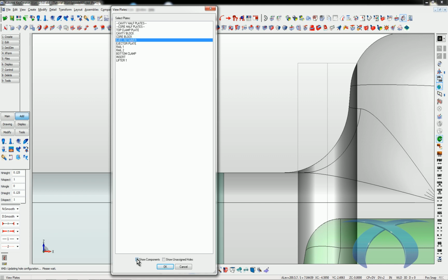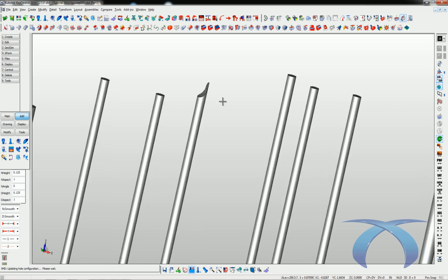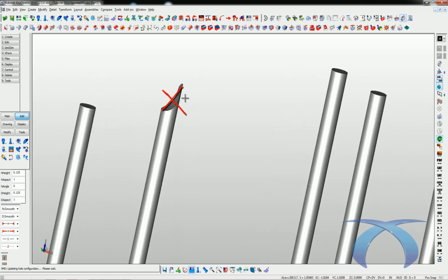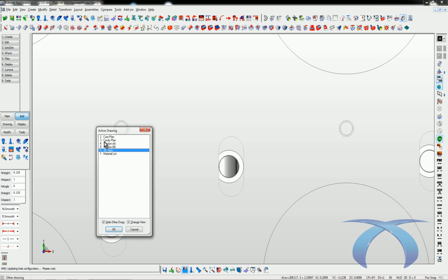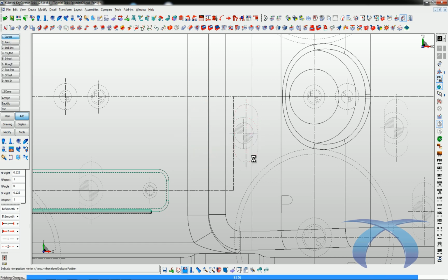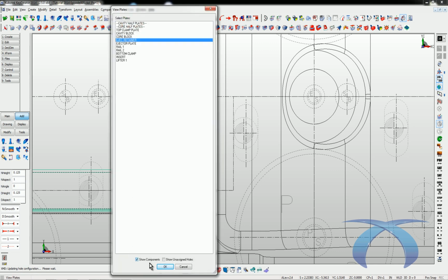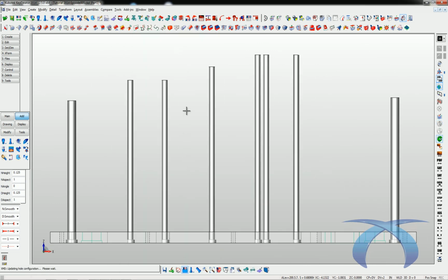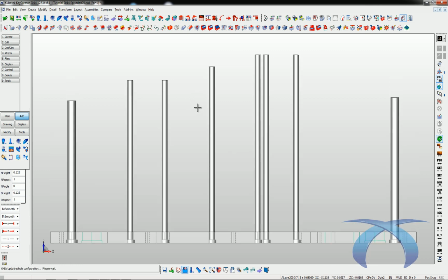have the contour added to them. So I can see, oh, I did not do a good job with where I placed that pin. And I'm able to fix that situation very easily by just shifting that pin over. So I can take this ejector pin and move it over to here, or I can move it up to here, wherever I want. Once again, I can do it in 3D so that I can see it a little more clearly in real time. Or I can switch over there and you can see now I've got it in a really nice spot, nice and flat. Okay.